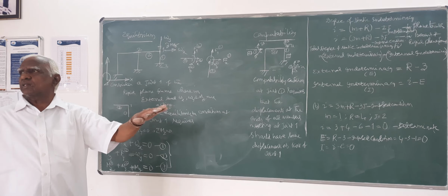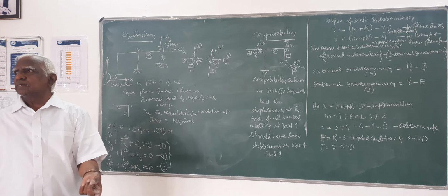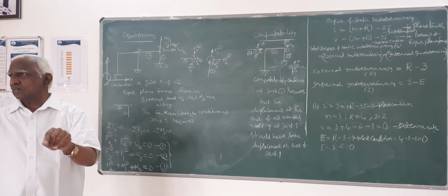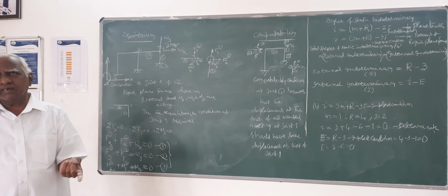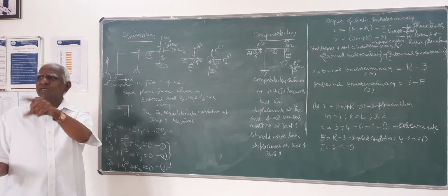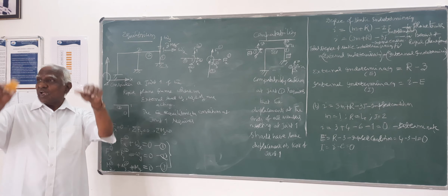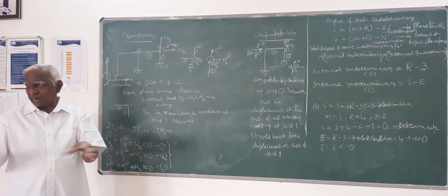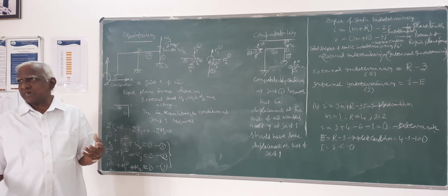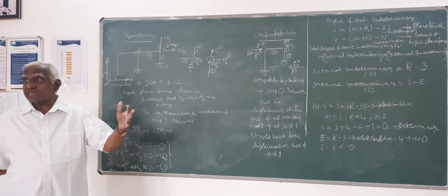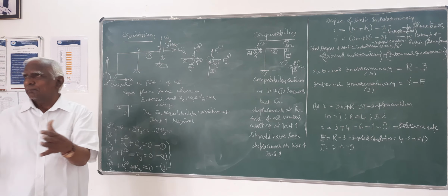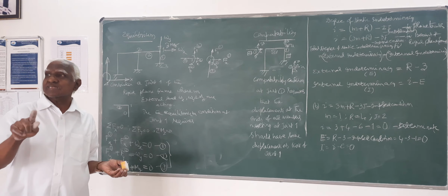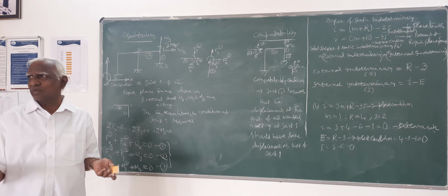Even if a load is acting on the members, we have to find the equivalent load at the joints, as if they are acting at the joints only. And if you have a number of loads like gravity load, temperature load, or settlement of support load, then you can just club their action together; that is allowed. That is called the principle of superposition.